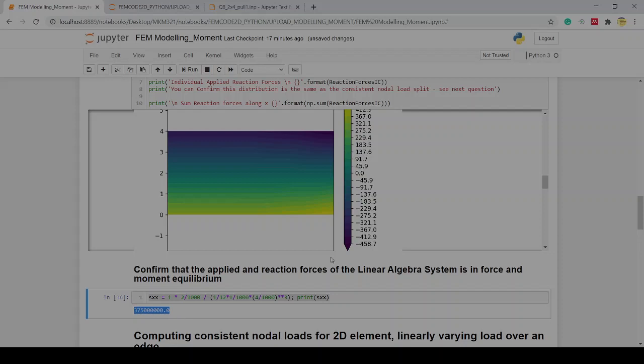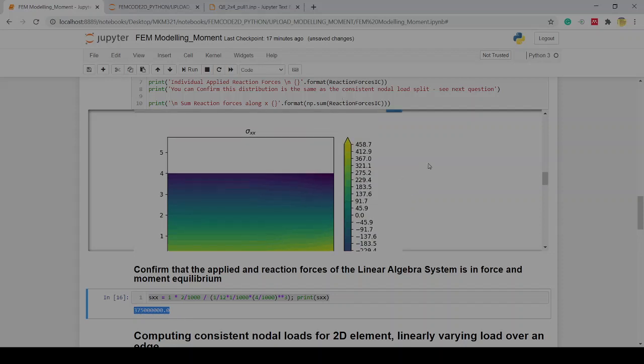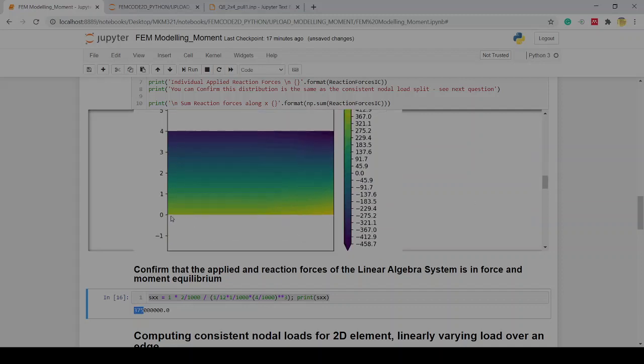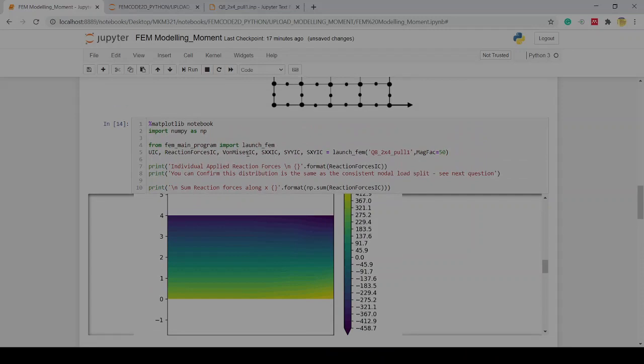Have a good ballpark of what we expect to see, so that we can interpret this result. Initially, just by looking at the results, we saw a 460 estimate of the maximum sigma xx stress, but that's much more than the 375 MPa we expect to see. So this is much larger. You can see also the color, the stress there is much lower. And you can go and open up the input file and verify for yourself what the answers are there.